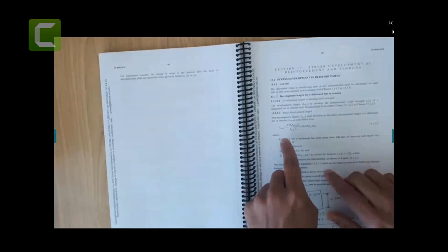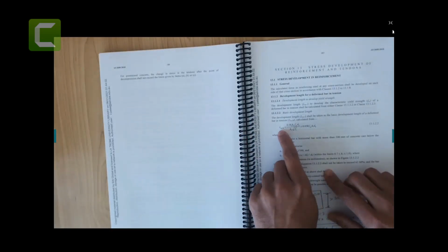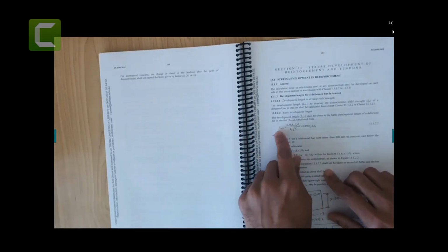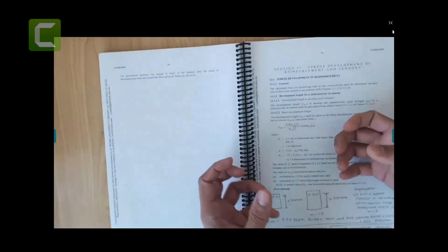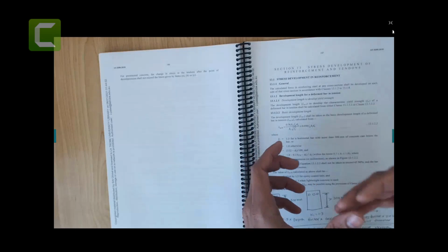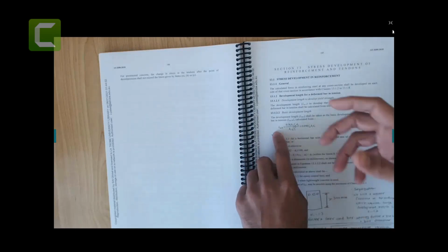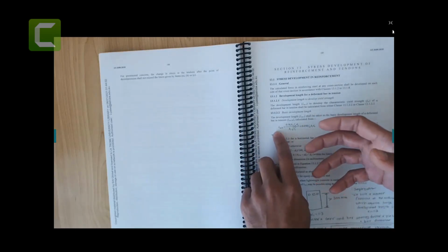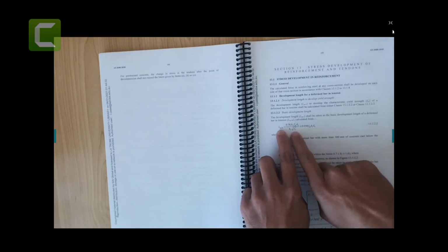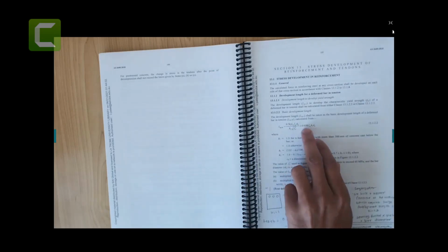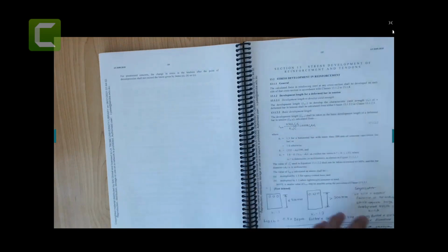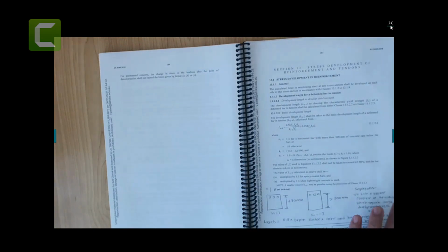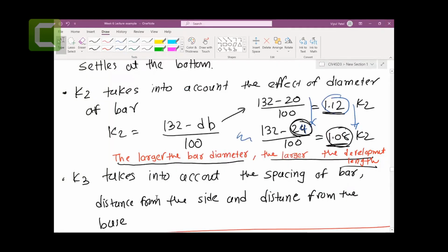Your rebar that you are trying to find is for tension, it's not a compression rebar. So the concrete surrounding that rebar is experiencing the tensile force, not the compression force. Therefore they are just targeting this one. And probably these are simple: fsy, K1 we already figured out, and dB is the diameter of your bar. So I hope that theory helps.